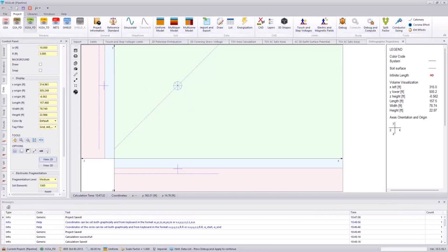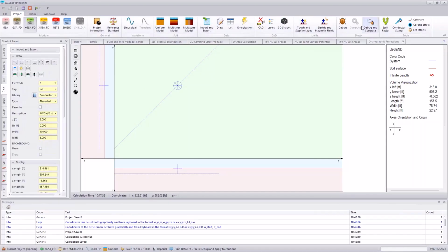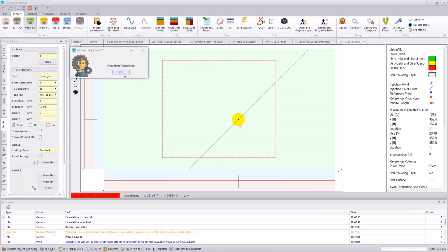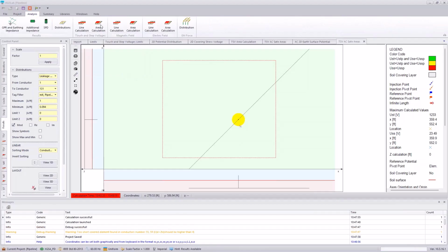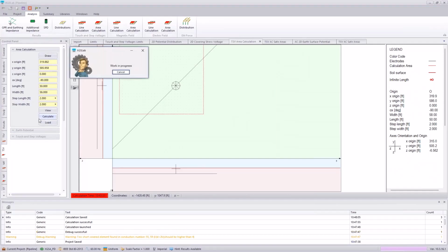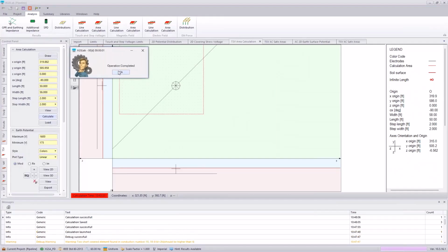And what we see, just to give a little example of what I want to highlight here, if we reran our analysis, before we had a touch voltage hazard at this point closest to our substation. When you introduce mitigation strategies, it changes how your system operates, and it can change things beneficially, ideally, but we can also start to see some hazards introduced by our mitigation approach.